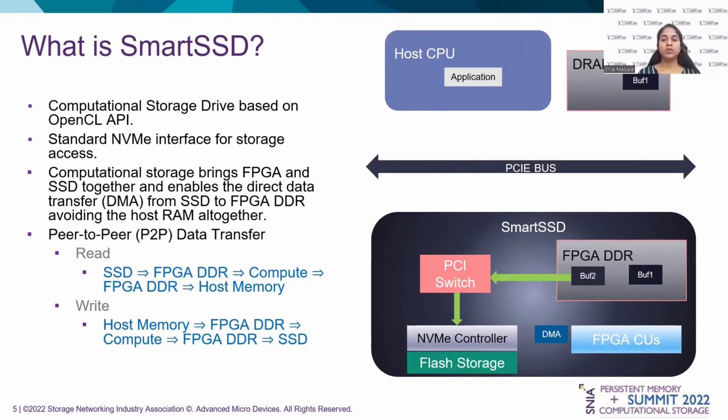This is possible because of the 3-port PCIe switch implemented inside the FPGA with its ports connected to host CPU, NVMe SSD, and the FPGA. The entire FPGA DDR is exposed to the host via PCIe bar, allowing the host applications to allocate data buffers from this memory and initiate data transfers directly to or from the SSD using standard NVMe driver stack.